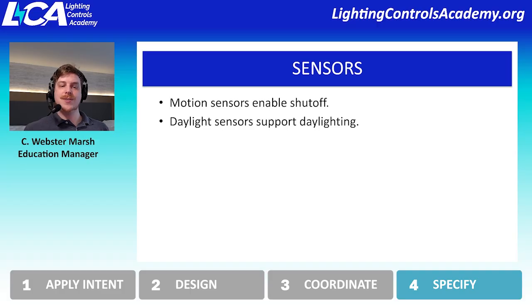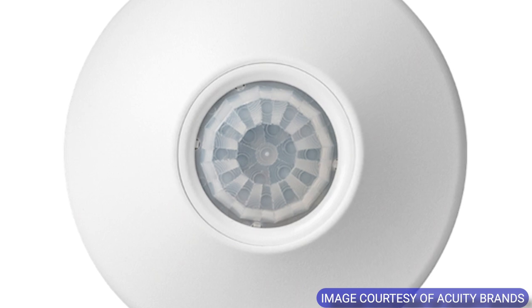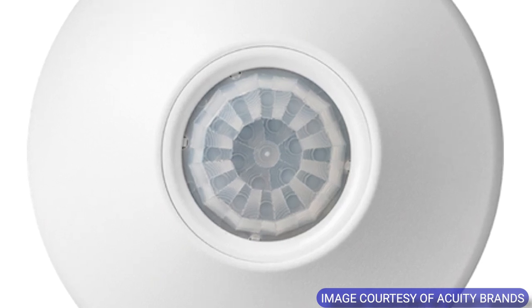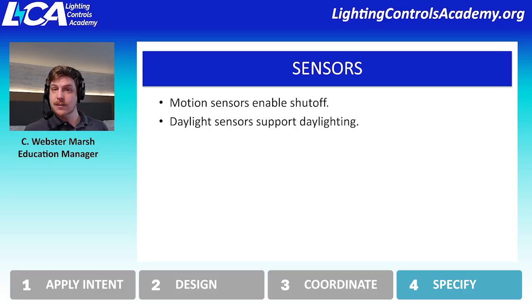And so motion sensors, or occupant sensors, have the ability to either turn lighting on automatically when somebody enters the space, or not turn the lighting on and wait until somebody manually activates the space, which is what used to be referred to as vacancy sensors, although we don't necessarily delineate that as much anymore. But either way, they will always shut off the lighting after a certain timeout condition.